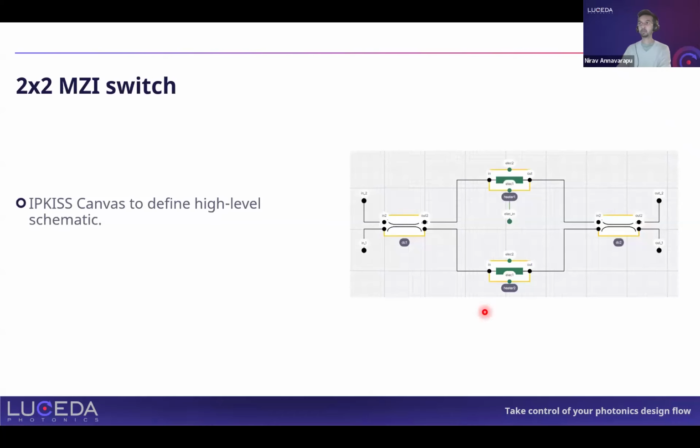There are two ways to approach circuit design. One is starting from a schematic of components which you'd like to place, and then write code around it. And the other is just to directly get started with writing Python code to draw your layout. We shall use the first approach. From a schematic point of view, a 2x2 MZI consists of directional couplers which are connected together using waveguides.